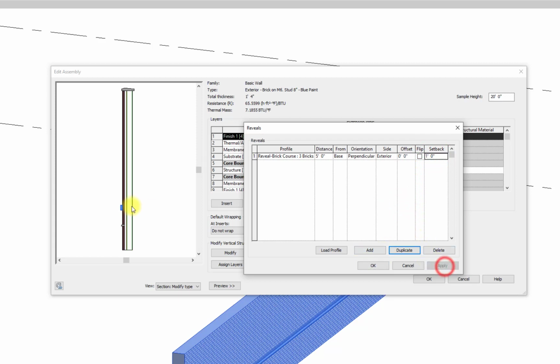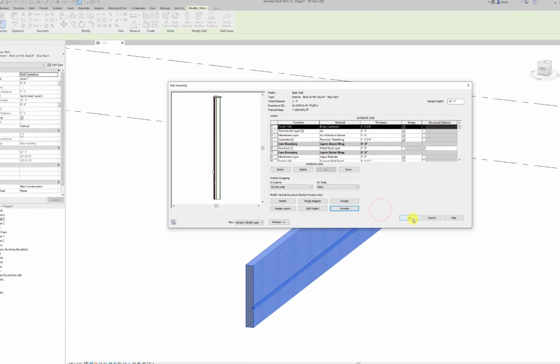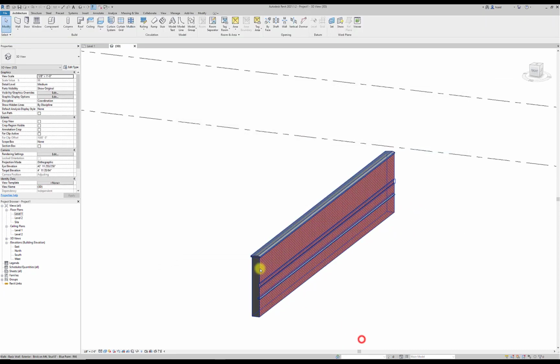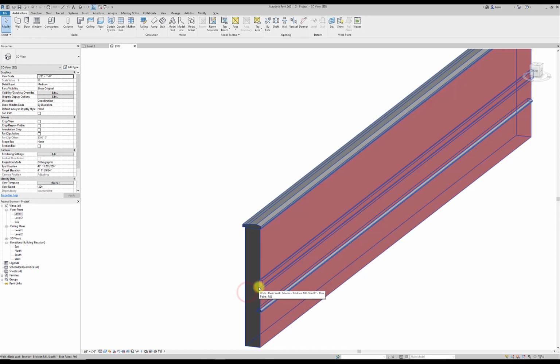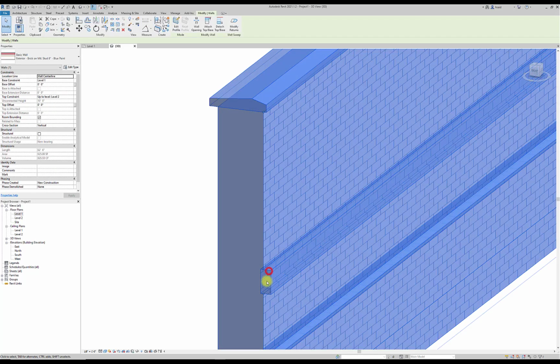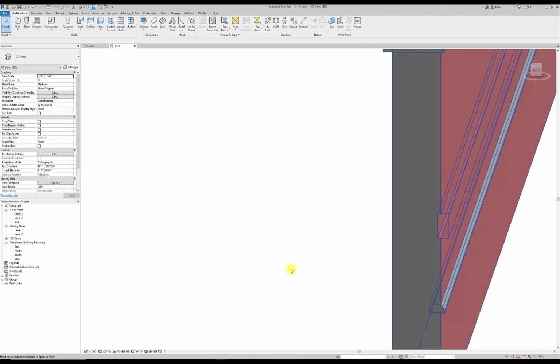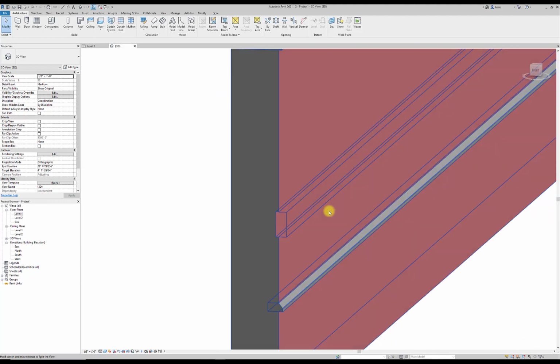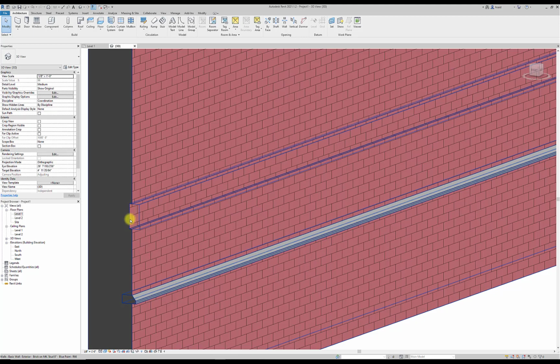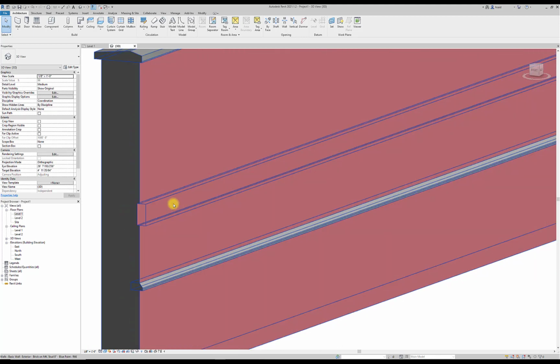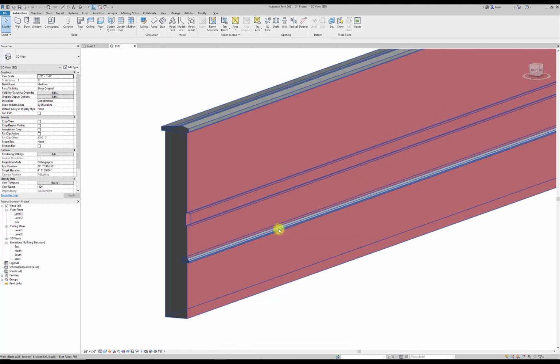And then if I say apply, this is kind of a void block that eats out of the material of the wall. So we'll see what I mean by that. But if I say okay, all right, apply. So this is the cap that I added, and this is the reveal. You see, when you don't highlight it, it's void. So it's eating out of the wall exterior, right? And it's three blocks, so like 3 block height of the pattern of the brick that you have.